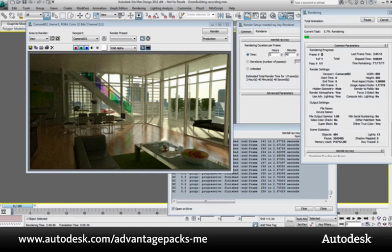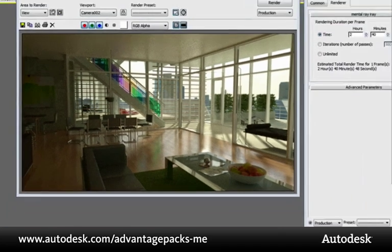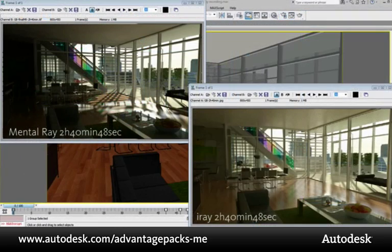You can now focus on applying physically accurate materials such as architecture and design materials or Autodesk materials, photometric lights, and settings that truly resemble what you experience every day. iray will give you a physical light calculation rendered image, not an approximation of the results. You can see here the image at about 25% completion, and already I can predict the final quality of the image. I will stop that render and show you both images that have been rendered for the same amount of time side by side.